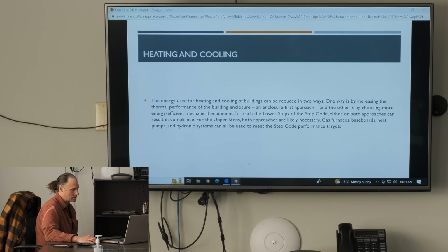High efficiency condensing furnaces use two heat exchangers to extract heat energy from the combustion of fossil fuels, natural gas, propane, oil, to heat the air. The incoming air is generally both recirculated return air from the building and makeup ventilation air. The energy demand of the furnace is based on the amount of air that must be heated to condition the home and the temperature difference between the incoming air and the temperature it must be heated up to. The furnace energy demand can be optimized by increasing the temperature of the ventilation air entering the system using heat recovery, or by using a dedicated ventilation system that uses heat recovery.